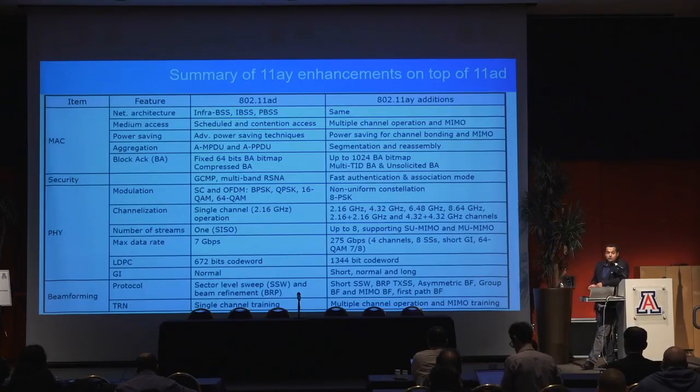And lastly, we also try to have beamforming that can be different for different applications. Some applications, and I'm going to be mentioning one later, you're not really interested in the path with the best signal strength or the best SNR necessarily. Some applications you may be looking for, for example, the shortest path. So there are these different ways of doing beamforming depending on the application, and if you bear with me for some time, I'll be covering that.